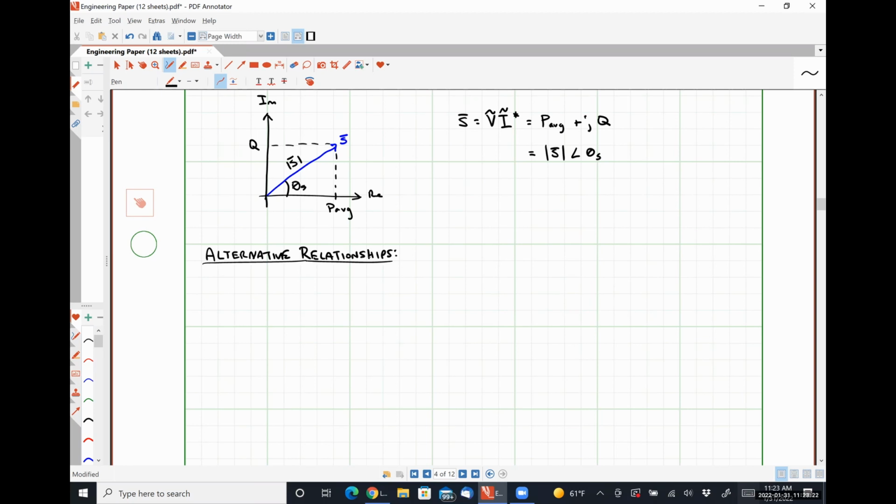Since Ohm's law in the RMS phasor domain is simply V equals I times Z: V is equal to IR in the DC or time domain, phasor V is equal to phasor I times Z in the frequency domain, and then if we put squiggles over our phasor voltage and phasor current, we have our RMS frequency domain relationship.